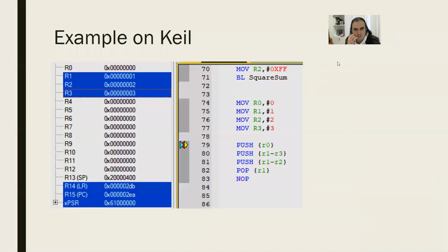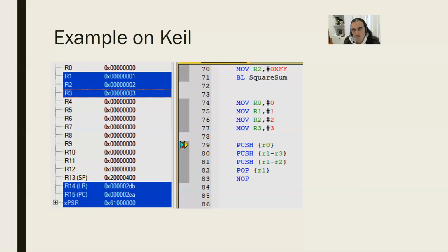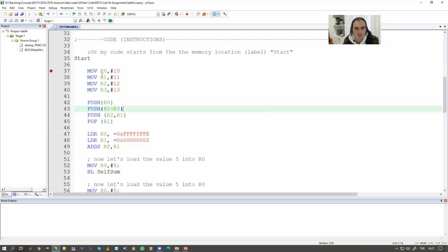I'm going to go over a simple example because this is a screenshot of Keil, as you will easily recognize. Very simple code, and I'm checking what's happening in each line. And after each debug line, when I press F10, I've taken another screenshot like this. So at the next slide, it is like I've pressed F10. So this will be what's happening when you work on Keil. When you work on Keil, you put breakpoints and use F10.